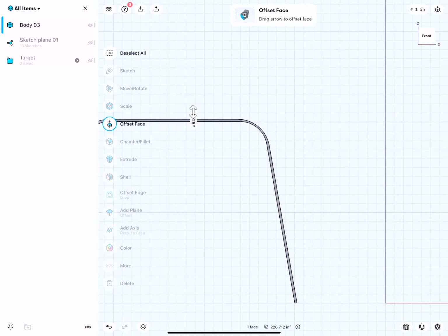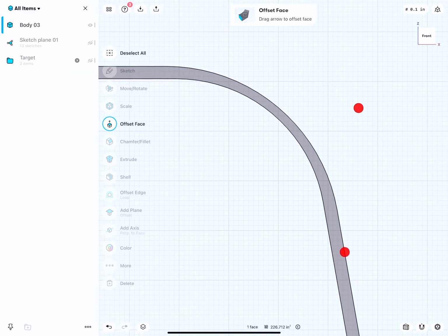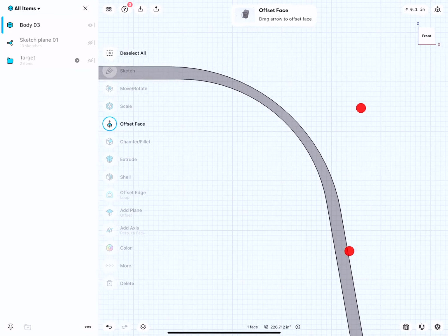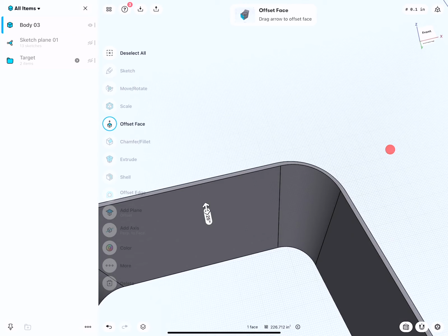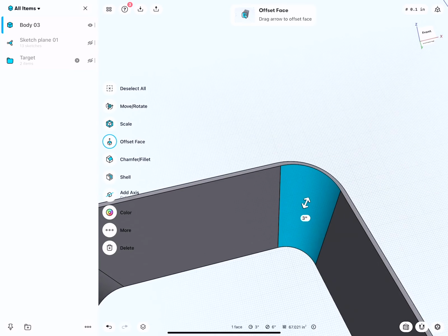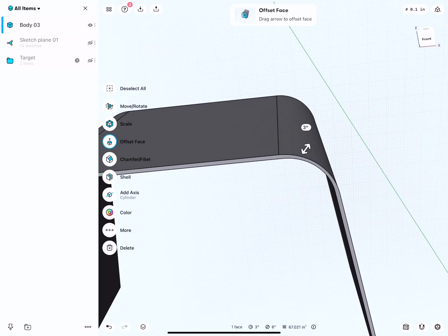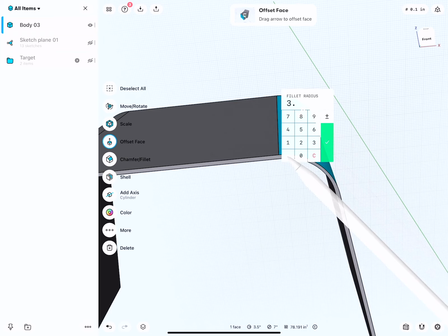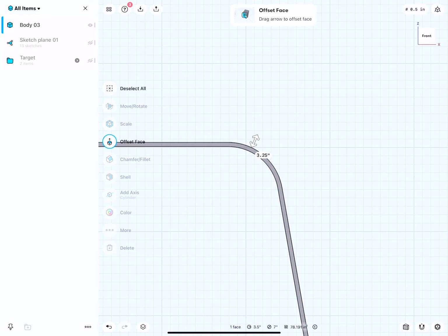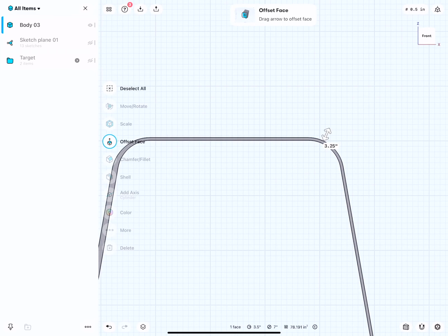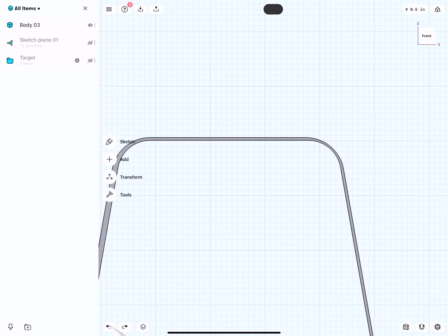Let's go to the front, and there's an error. So if we zoom in, you can see that the fillet or the rounded edge is not really adjusting correctly. It's actually very easy to fix. So the inside is 3 inches, and when I select the outside, you see this is still 3.5. This actually should be 3.25 since we removed a 1/4 inch. There, you see now everything is updated. So you see it's actually really simple.